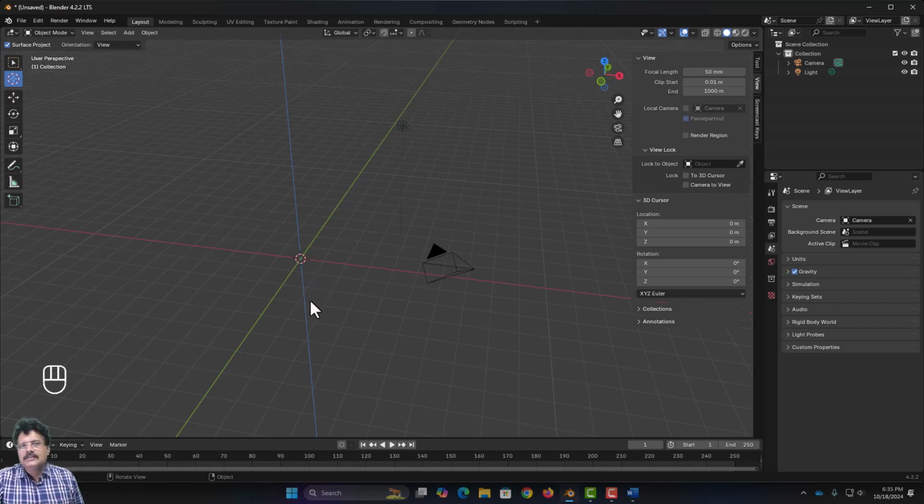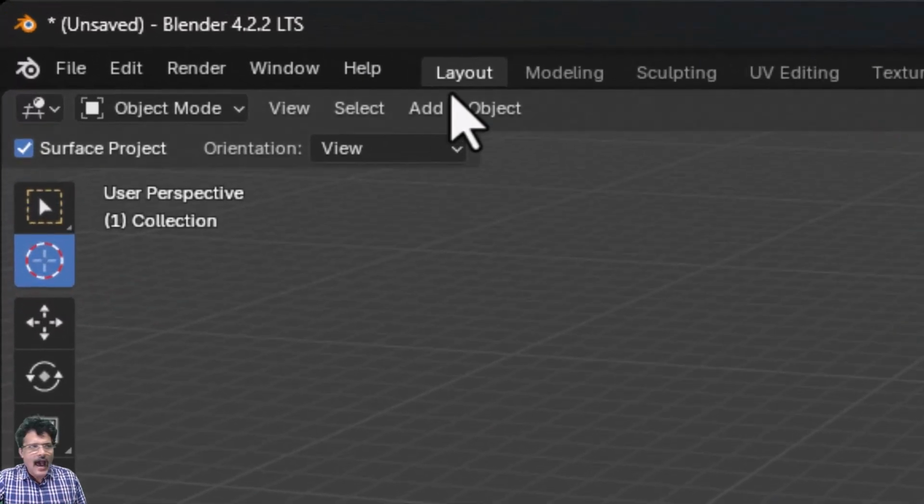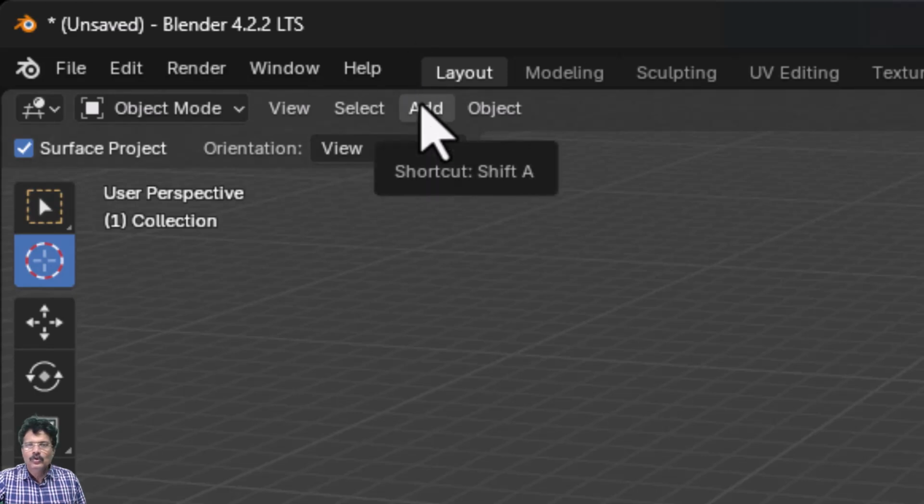And now knowing this, the very first thing we are going to do here in 3D is to first create our model. Whether it might be a cube, cylinder, or a table, chair, sofa, any object you want, this process we call modeling. And to start doing modeling, Blender provides us some basic objects and we call these primitives. I can come here to add, and even for this add menu, the keyboard shortcut is Shift plus A.